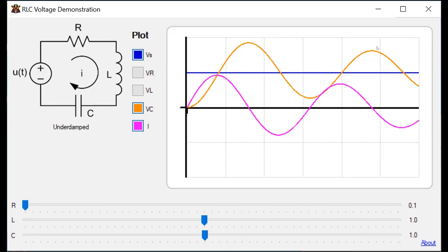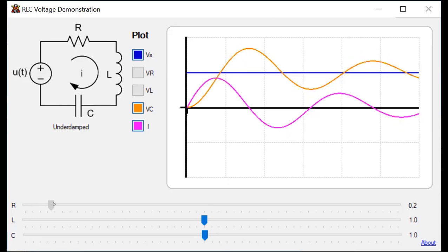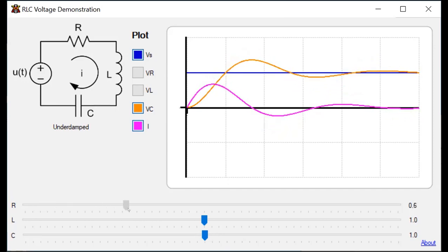So here's the big difference between first order and second order. There are 3 different equations that control what's going on. Here, when there's not much resistance relative to the amount of capacitance and inductance, you see current and voltage, you see energy sloshing back and forth, and you see sinusoidal waveforms. Sinusoidal waveforms that, because of the resistance, slowly have their energy taken away. And as you increase that resistance more and more, it decays away faster and faster.